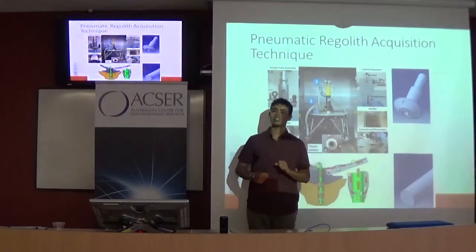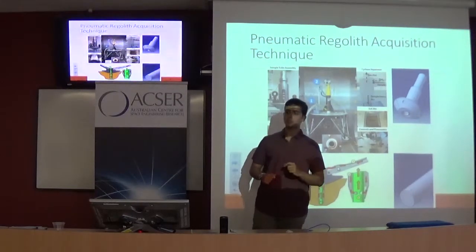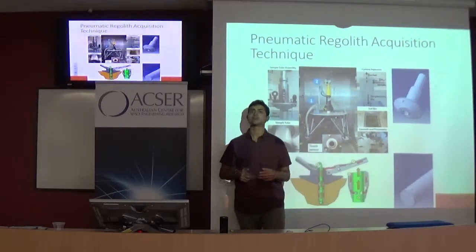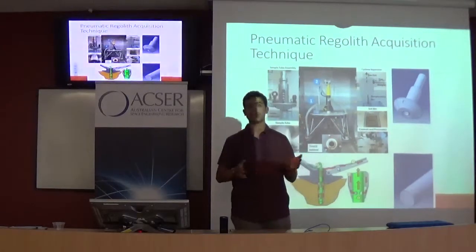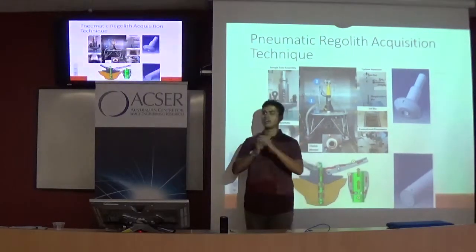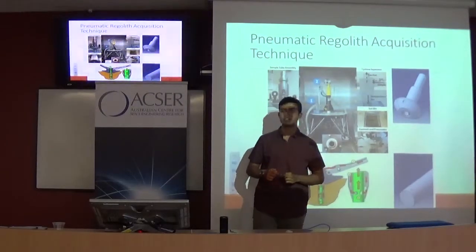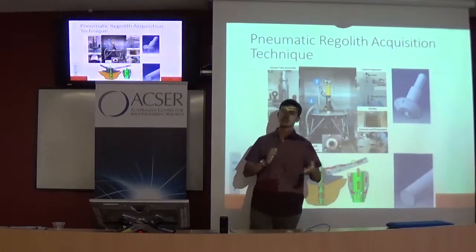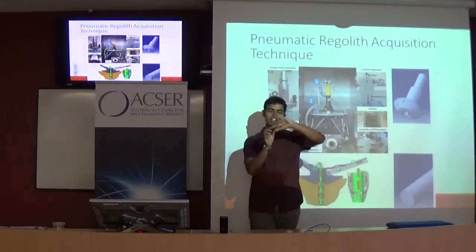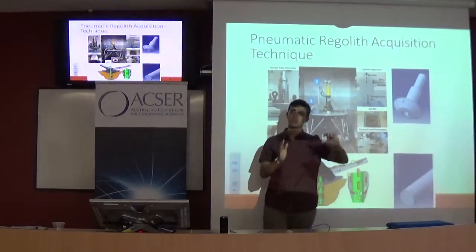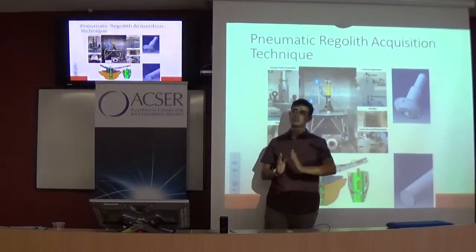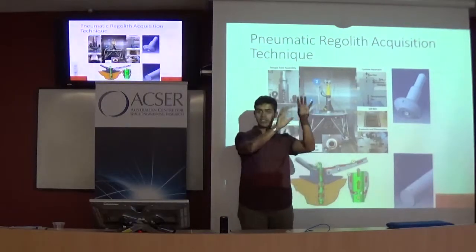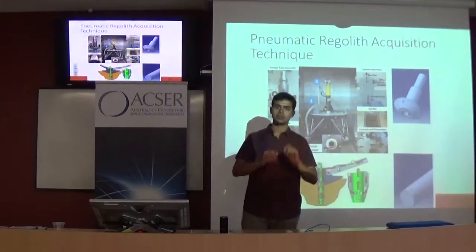And another thing that I didn't mention is that regolith is very abrasive, especially on the moon. If it impinges on the internal surfaces, it can damage and sometimes rupture them because the grains are really sharp. Especially on the moon, where there's no atmosphere, there hasn't been any rounding of these grain particles. They're very sharp little particles. And also on Mars, you expect to have this. So it becomes important to understand how to force the flow. If you have, say, a 90-degree pipe, you want to ensure that your regolith is flowing in an optimal path through that pipe and it is not being stored. That was another area which I didn't focus on, but primarily these were two areas.